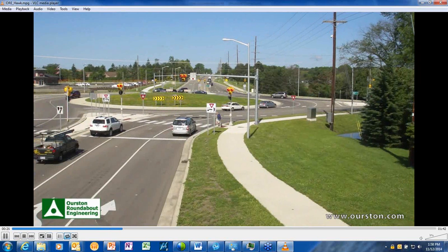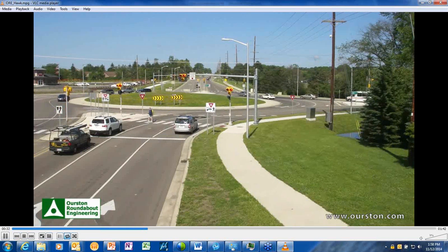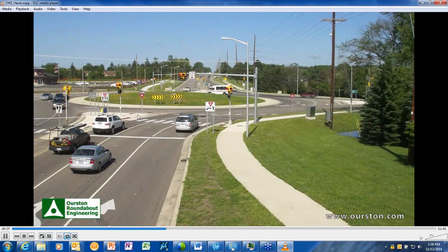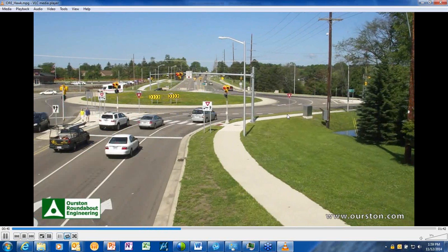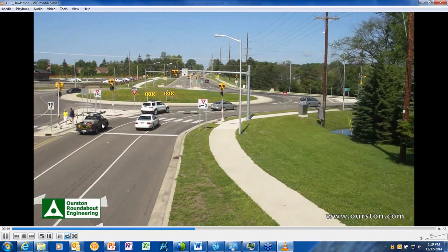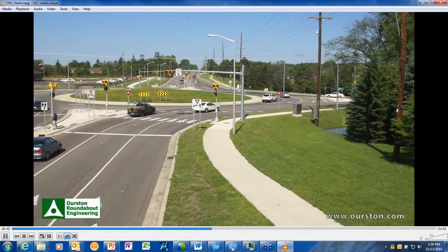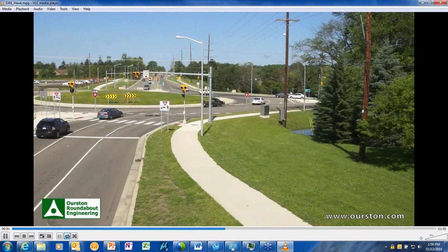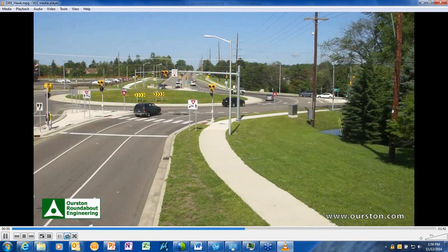If the pedestrian volume is very low, you know, having a crossing accommodation in a high volume roundabout situation where the crossings are indiscriminate, and let's say it was a school and they were pushing the button every 30 seconds, you could conceivably impact the roundabout capacity and neutralize any benefit of roundabouts for capacity, because the crosswalk is constantly occupied. We ran into a situation like this in a study, at least, and I want to show you a little video clip here.